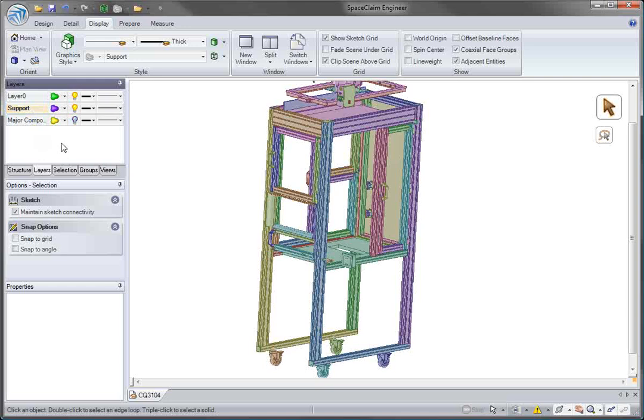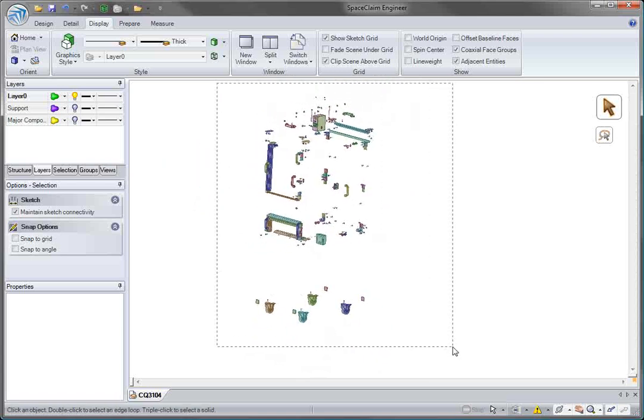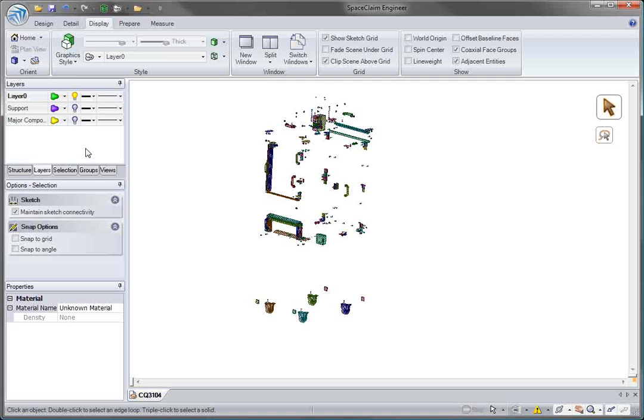And once we've finished placing our components on different layers, we can rename them. And notice you can't rename layer 0. So if you want all your components on there, you'll probably go through and select all of them and make a new layer. I prefer to not have anything on layer 0. So now we can rename this. We'll just name this small stuff.